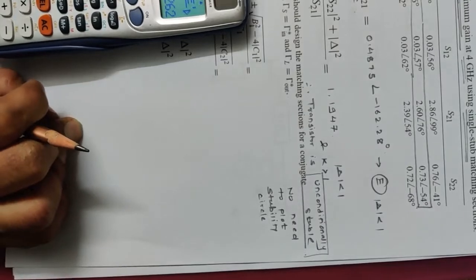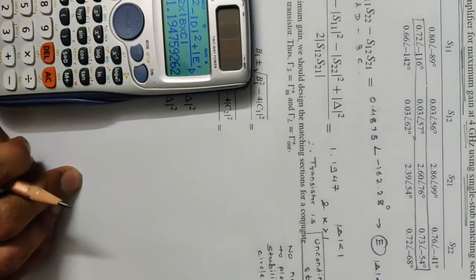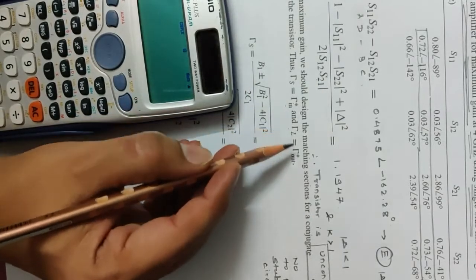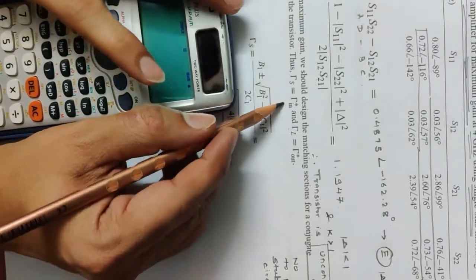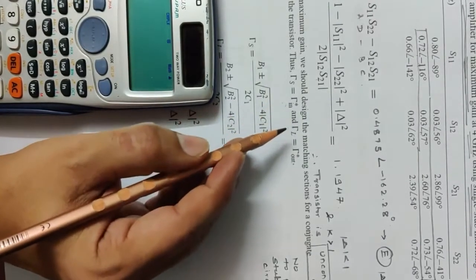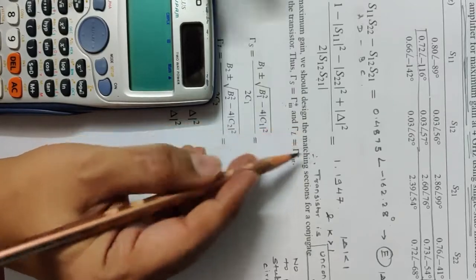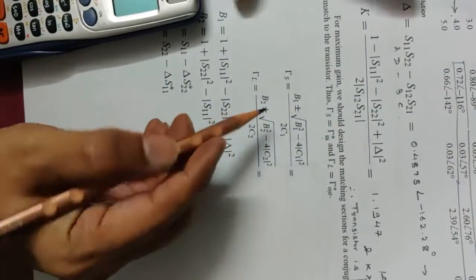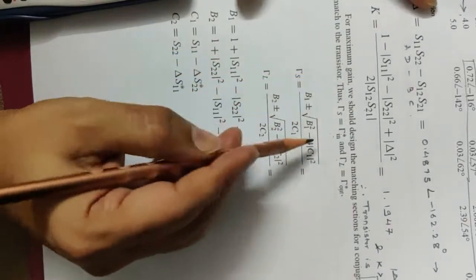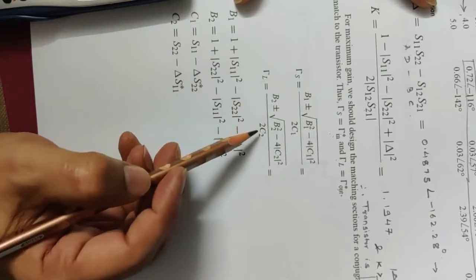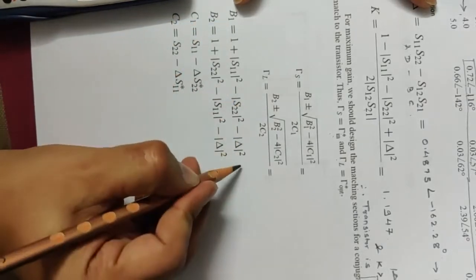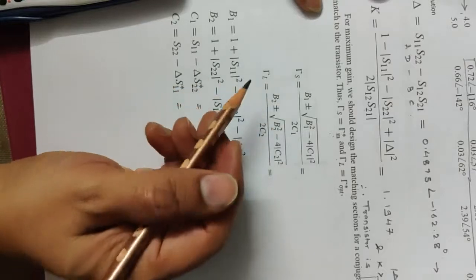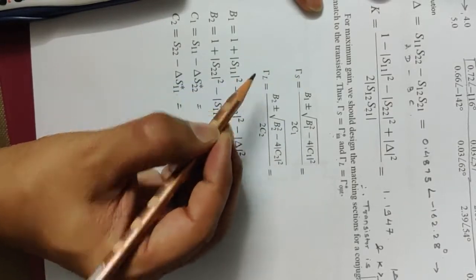So now we have to design for the maximum gain. As you know, for maximum gain there should be a complex conjugate matching. So gamma S should be equal to gamma in star and gamma L is equal to gamma out star. But gamma in formula also involves gamma L and gamma out formula involves gamma S. So after simplification of this one, it results into this formula. So gamma S and gamma L can be selected in this manner, where this B1, C1, B2 and C2 are defined like this. So first we'll calculate these parameters B1, B2, C1 and C2, and then we'll calculate gamma S and gamma L, and then using Smith chart we'll proceed for the matching of gamma S and gamma L.